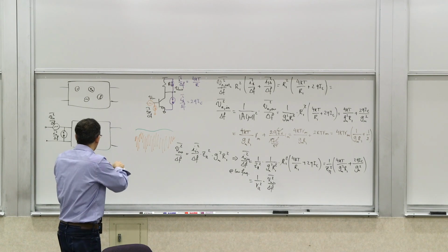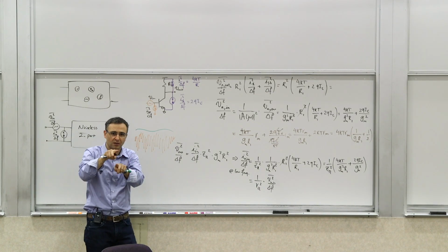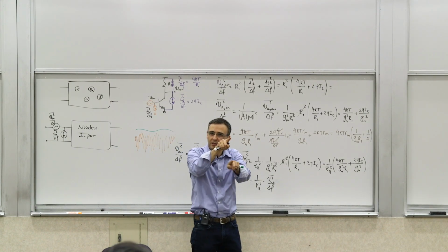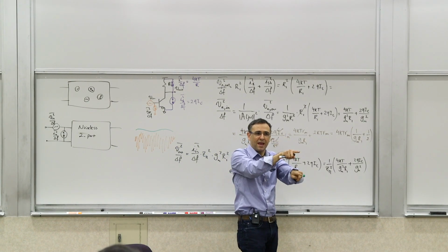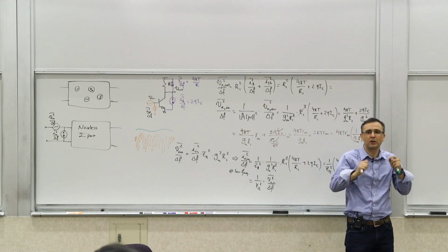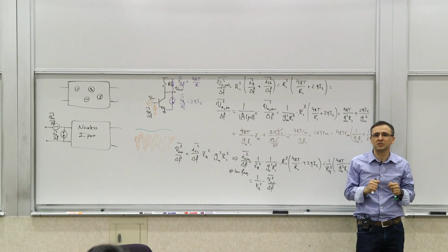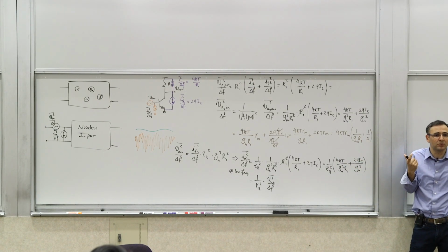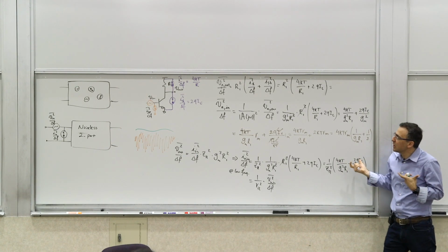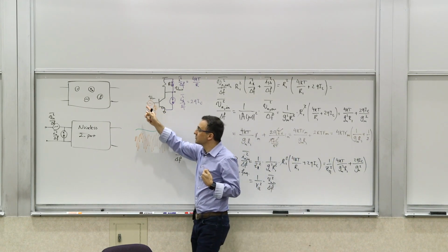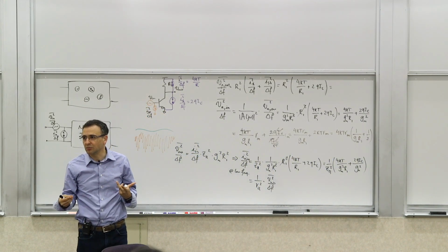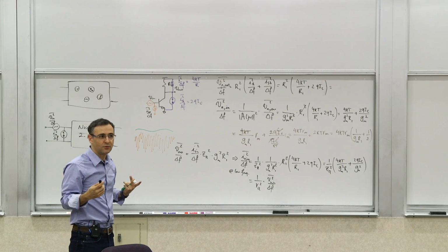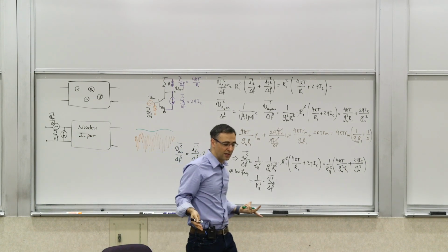If you look at the random fluctuations of these things, if this is the current one and this is the voltage, they're going together completely, right? They're doing the same thing as they go. They're fully correlated, 100% correlated, because they're caused by the same sources. This is an example of the same source. We need both of these things to take the effect of any arbitrary impedance at the input, but they are really capturing the same effect. And if you treat them like uncorrelated sources, then you won't get the correct results.